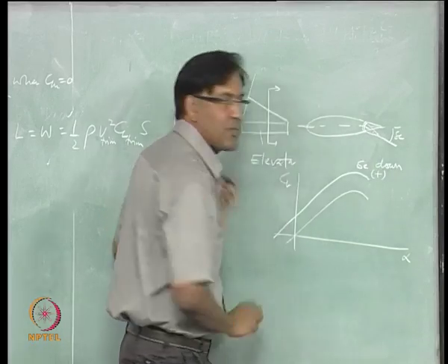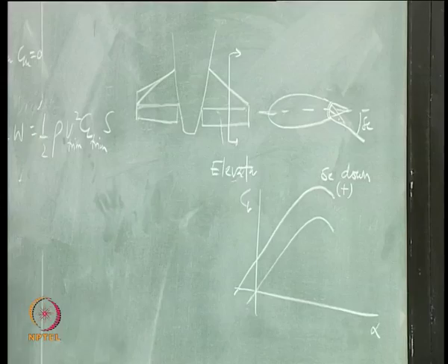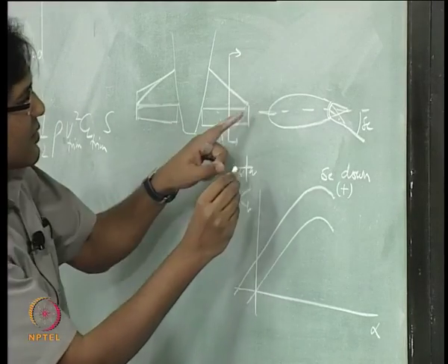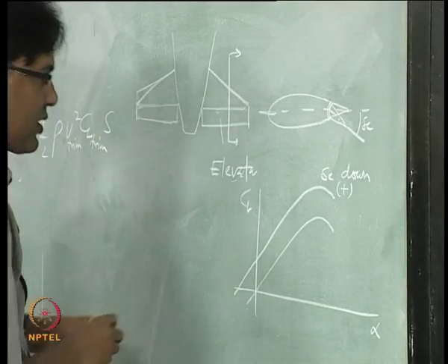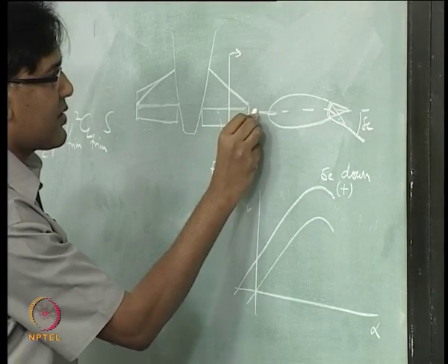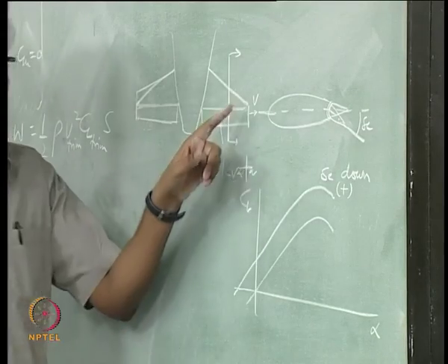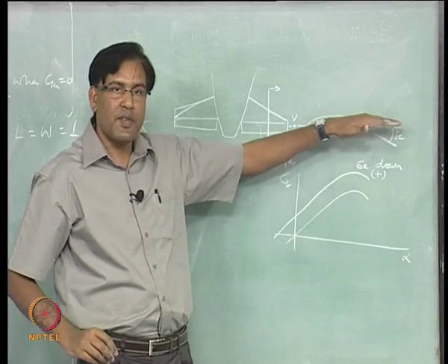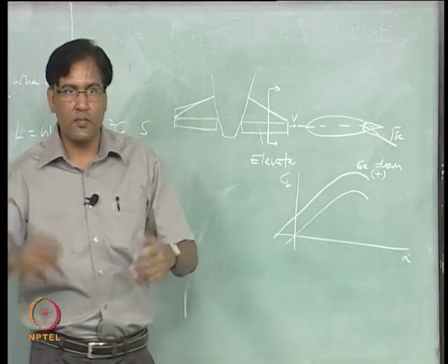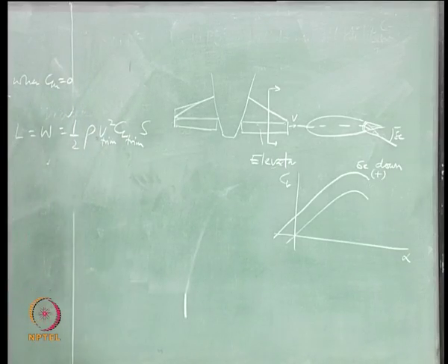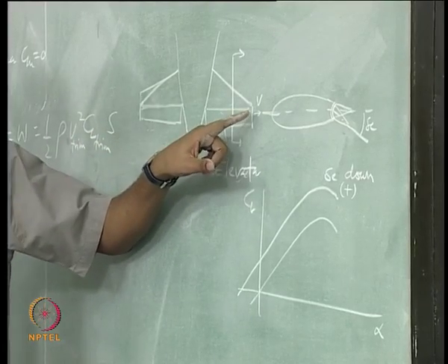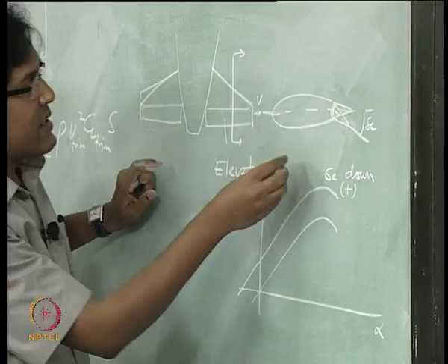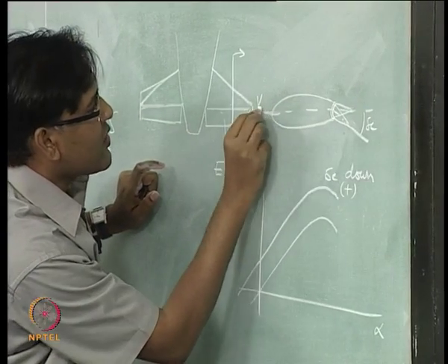We will take this as positive, remember this convention, okay. And the angle of attack, so for 0, this was the direction of the flow V, and if it is a symmetric airfoil and if there is no deflection of this flap, then you are going to see an angle of attack which is 0, is it not. But now keep this relative wind velocity in the same direction and change this elevator, what you see is this.